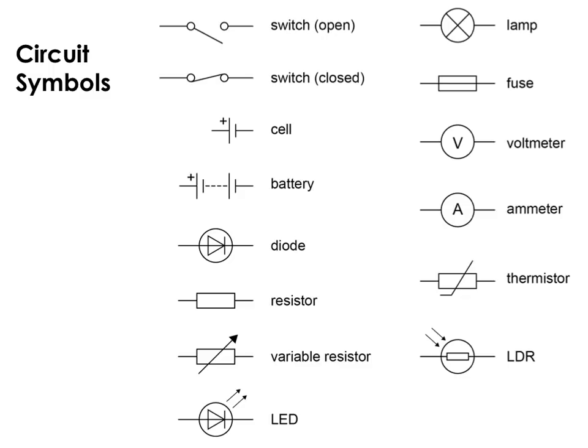The other resistors that we have are thermistors. They're heat dependent and they kind of have the hockey stick style that goes through them, and basically if you increase the temperature in a circuit with a thermistor, then the resistance of the thermistor will decrease as temperature increases. Obviously if you want to then cause an increase in resistance, you would decrease the temperature. So a temperature decrease will cause an increase in resistance for a thermistor.